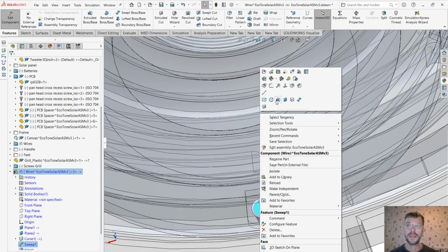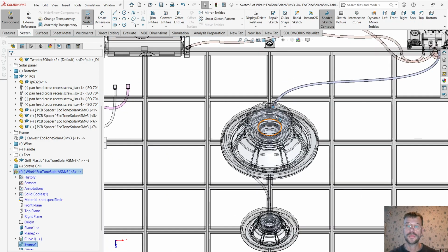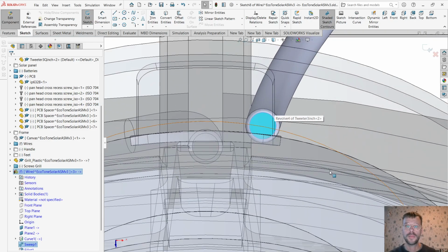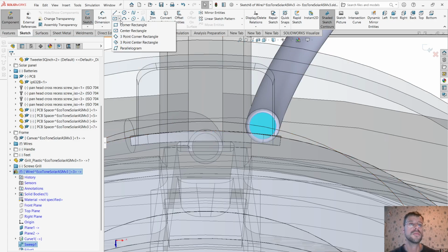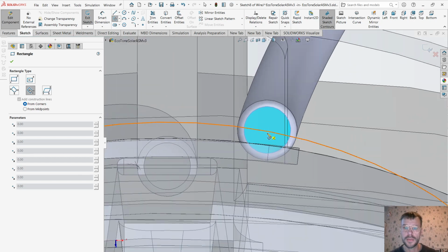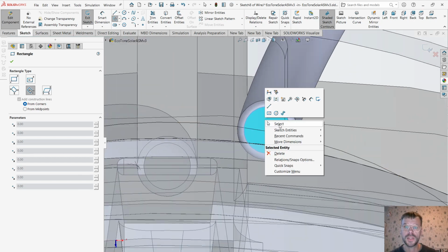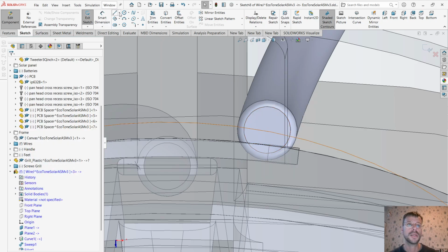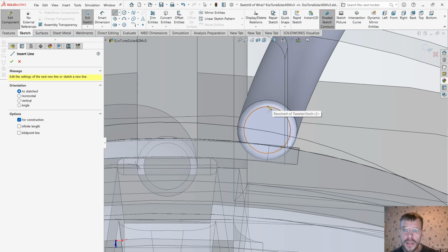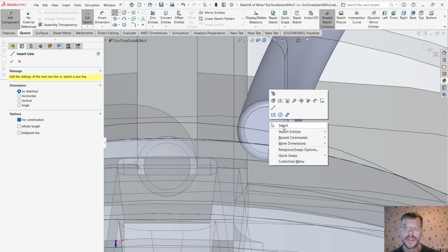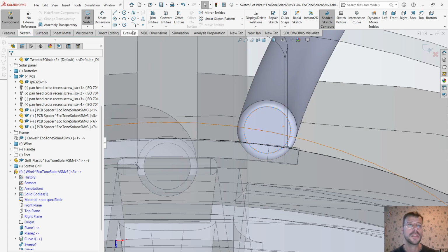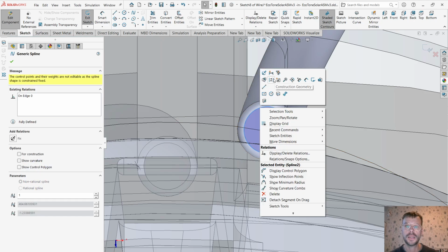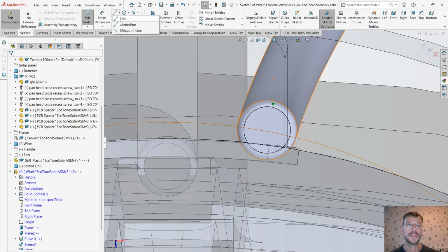It's here. Click it. Right click it. Sketch. Here. I want this to kind of go with this edge. So let's make it with the 3-point center rectangle. Let me just exit this because I want something to, let's just exit that as well. So we choose this one, go convert entities, right click it, construction line, center line.